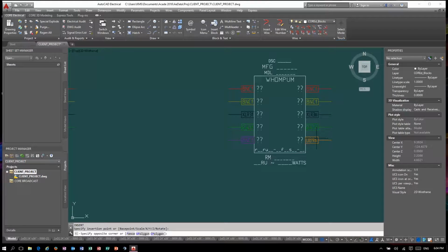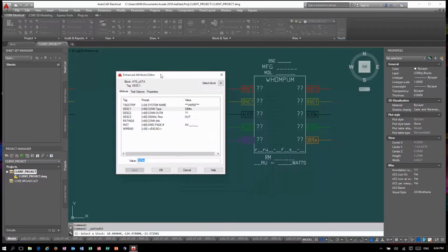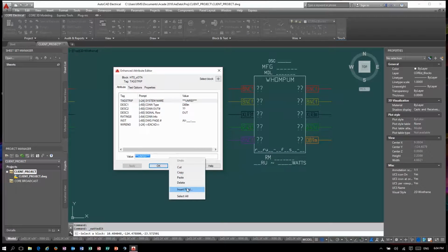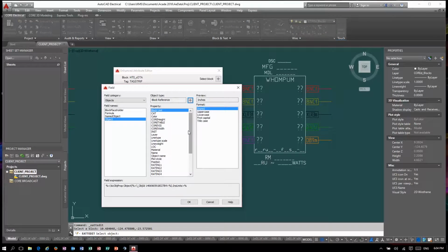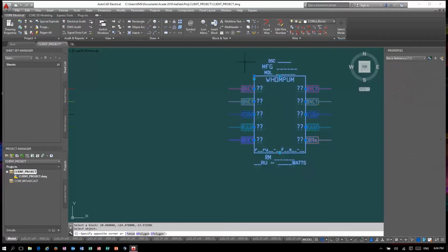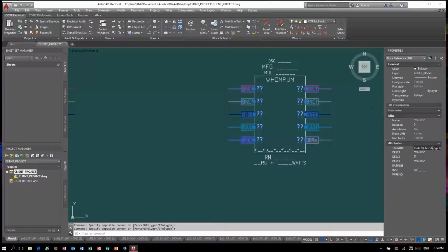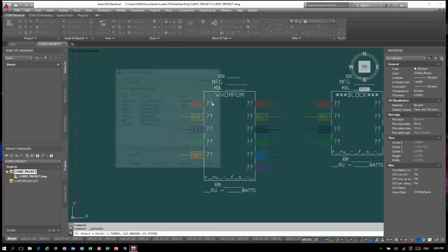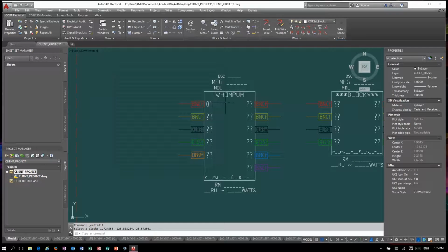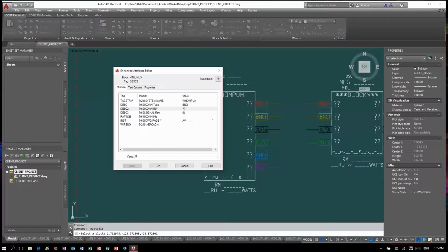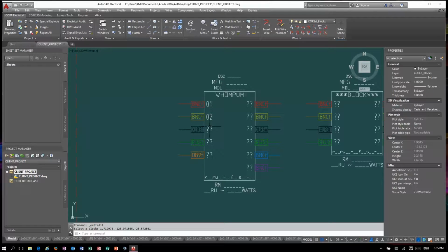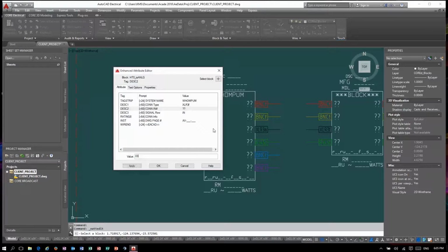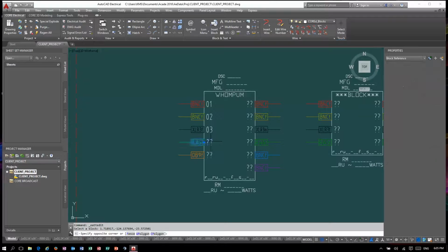This tool also identifies the requirement to use unbalanced to balanced transformers, signal converters, and adapters required between broadcast and consumer-related devices. By default, our application performs secondary verification of device, connector, and wire references, as well as duplication of devices independent of system names. Auxiliary information is also analyzed to identify missing system components, flags, and wire data required to calculate power, heat, conduit sizing, cable length, connector type, and part numbers.